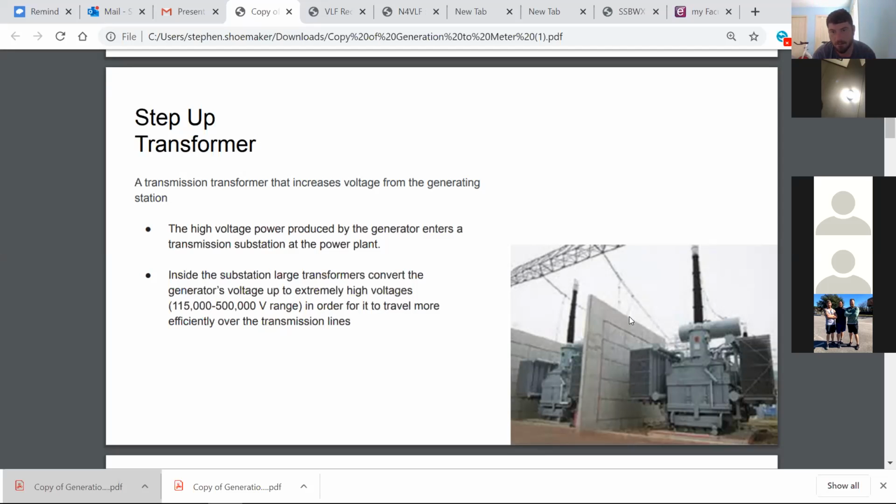You'll see this in the more modern generating stations, and sometimes in substations. This wall that they put in between is actually an explosive barricade. If you have a catastrophic failure of the transformer right here, the damage is funneled up and won't damage the next transformer over. These transformers, gentlemen, are grossly expensive.